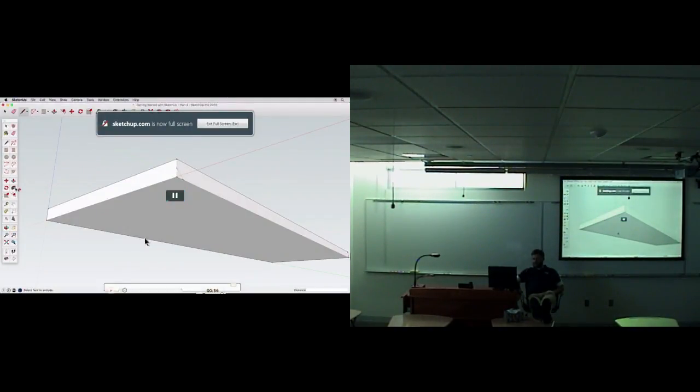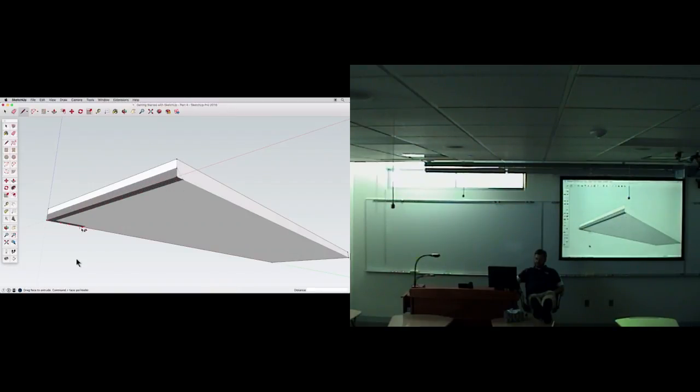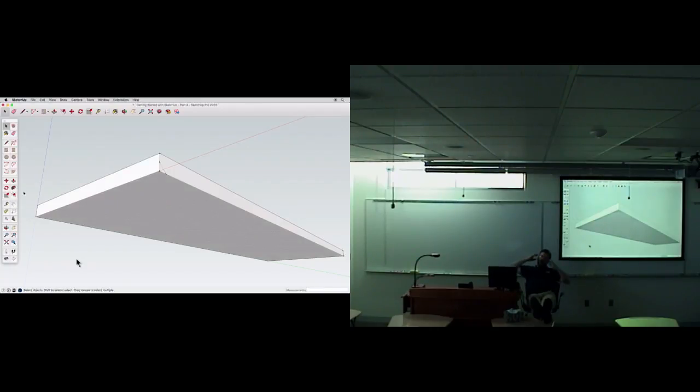Follow Me tool to create a chamfer. So here's the drag manually method, to follow the surface around the edges, but there is a quicker method we can use. Because we want to chamfer the entire lower surface, we can pre-select that surface, then pick the Follow Me tool and click on our angle to finish.